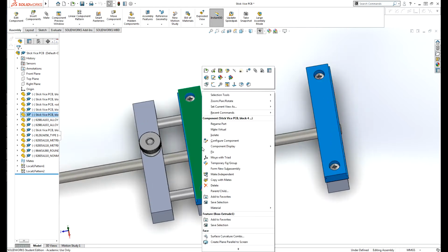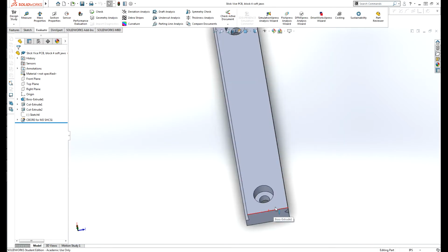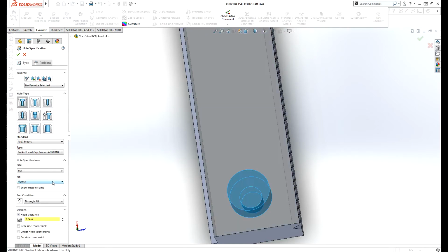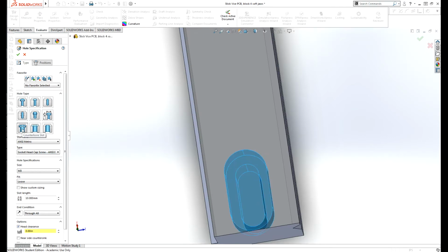Knowing this and exercising good design principles will alleviate this one downside to 3D printing. In general, a good design principle is knowing what manufacturing technology you're going to use to create your part. With 3D printing, it's good to have relaxed tolerances where applicable, or, for example, using slots instead of holes when you're mating two parts.